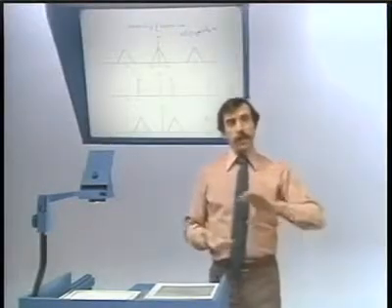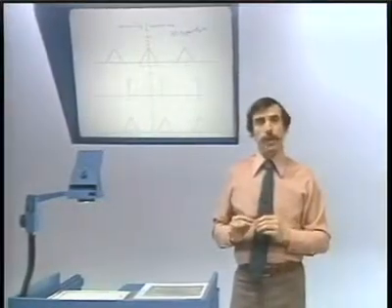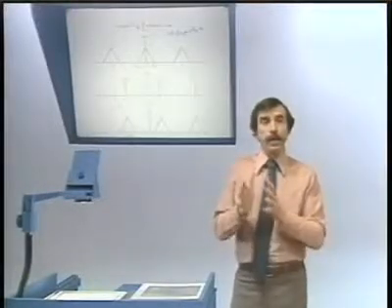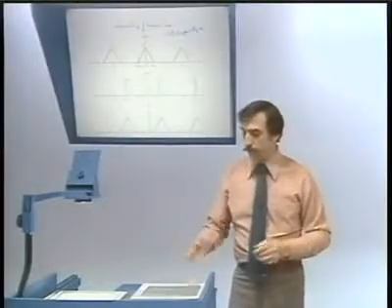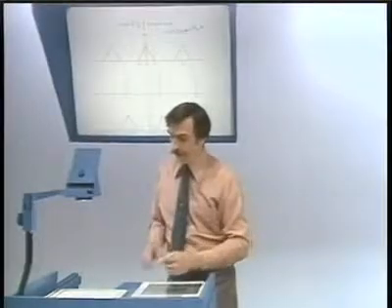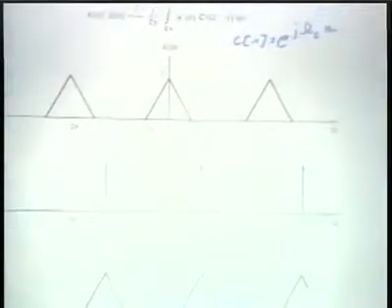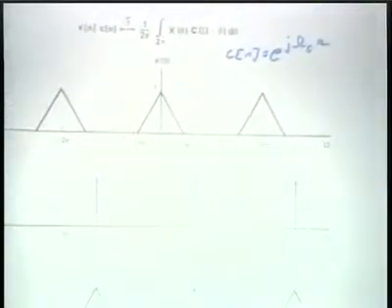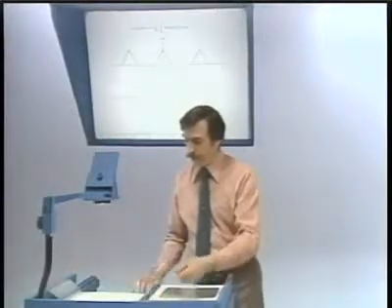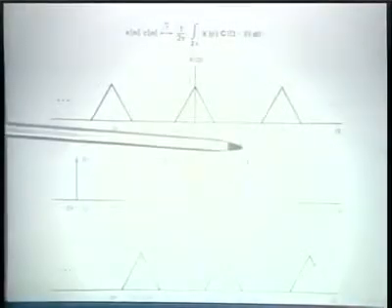Now, in the continuous time case, we demodulated, when we had a complex exponential carrier, by essentially just shifting the spectrum back. And in fact, in the discrete time case, we're able to do exactly the same thing. So if we were to replace c of n, which is e to the j omega sub c n, by c of n equals e to the minus j omega sub c n, the resulting spectrum would be an impulse train, as I indicate here.